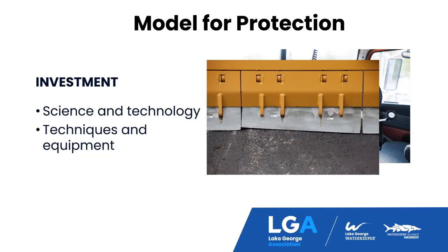So with the equipment and how that gets better, there's also the use of roadside cameras, so you can actually take photos of the roads and see what the conditions are and see, number one, do you need to go out right away, or can we wait an hour? When you apply brine, what are the conditions of the road? So set these up at key locations and use that technology.